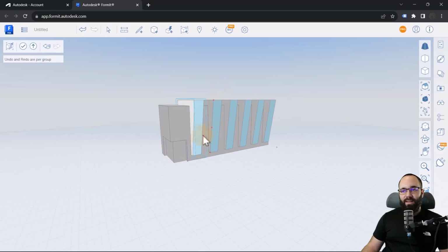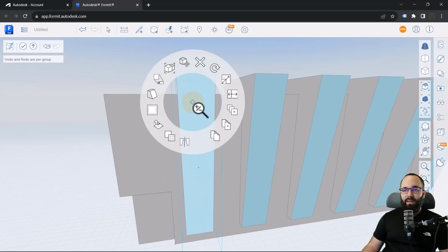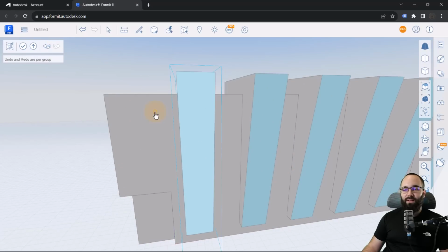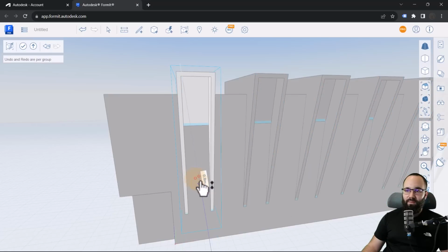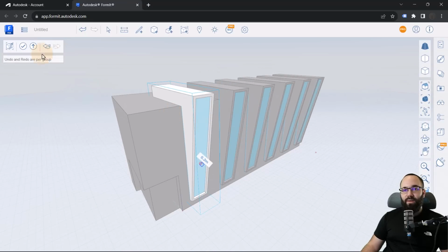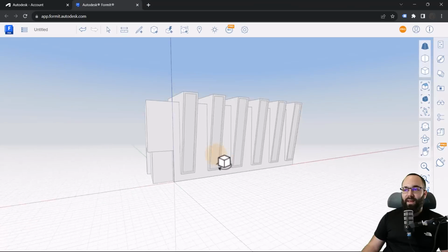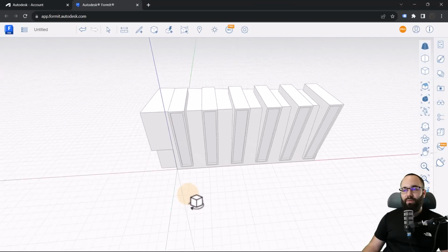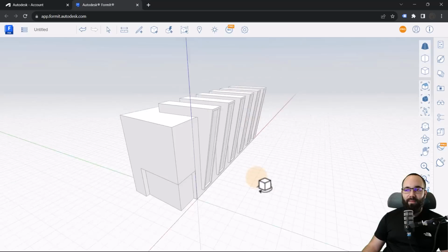Finally, I'm going to select this edge here. I'm going to right click on that, and here we have this face or offset face function. And now I can offset it by the value of 0.2 meters, hit enter just like this, and then I can select this face, push it in a little bit if I want, just like that. Yeah, definitely looks good. So there we go. I can just now hit finish. And now this change has been applied to rest of this group members.